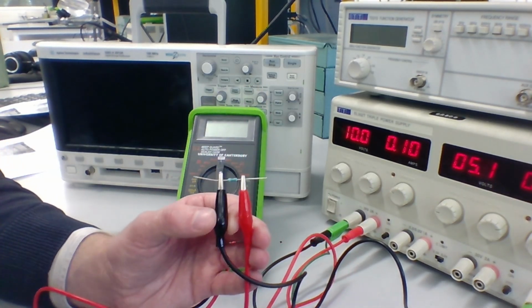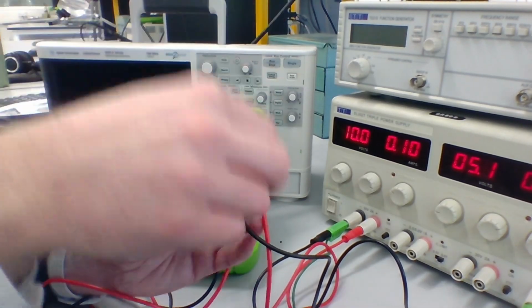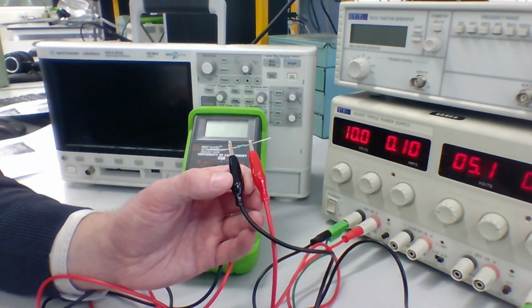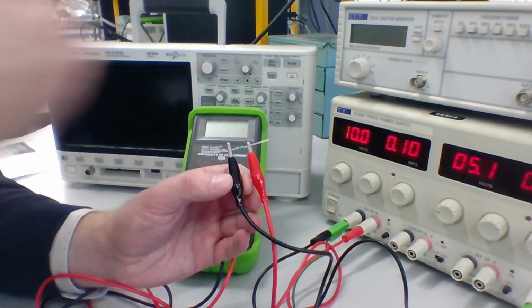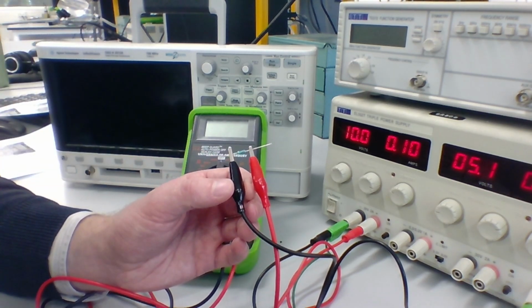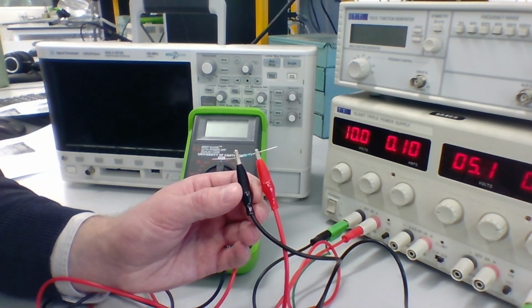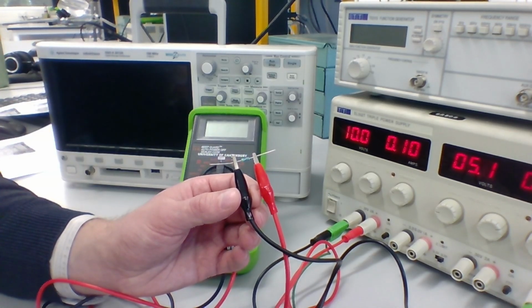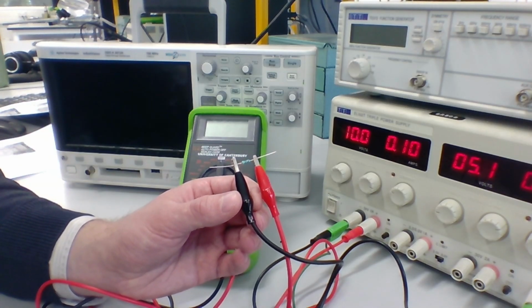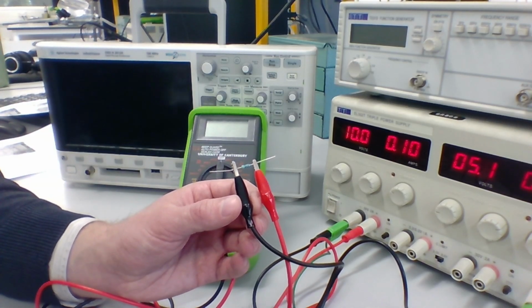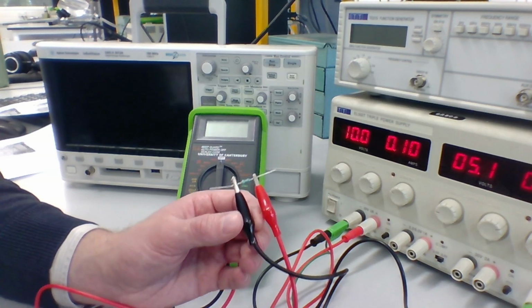That means we're going to need to jump in between somewhere the power supply and the resistor. In this circuit, it won't matter where we do that. We only have a single component. In other circuits, it will matter where you do that, because that will determine which current you're measuring in your circuit. So always just have a quick think about where you want to measure things based upon what you want to know.